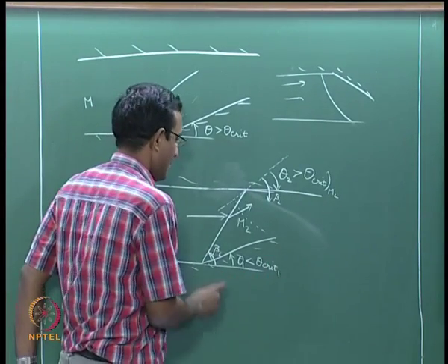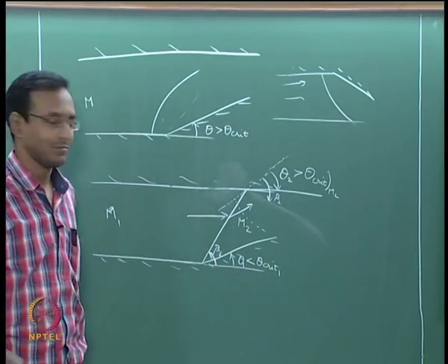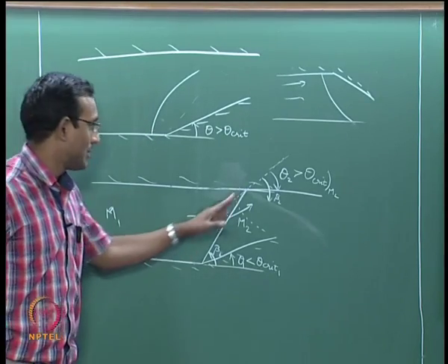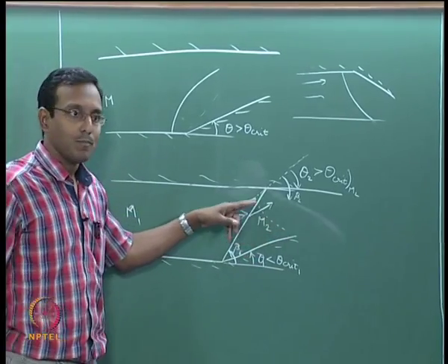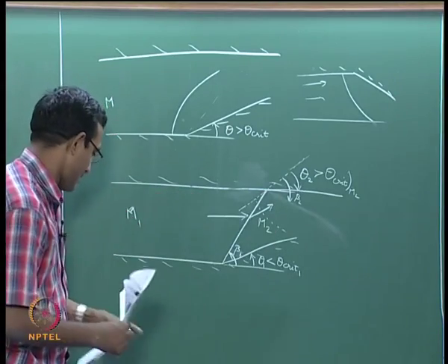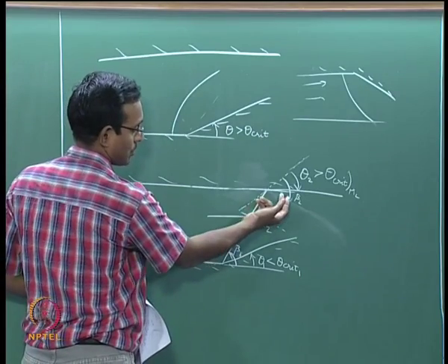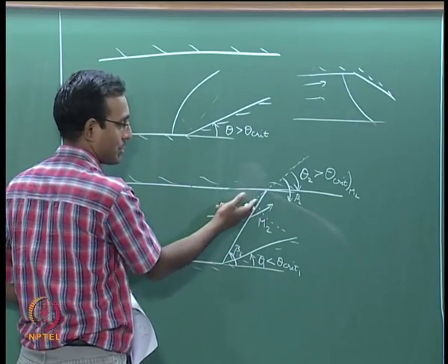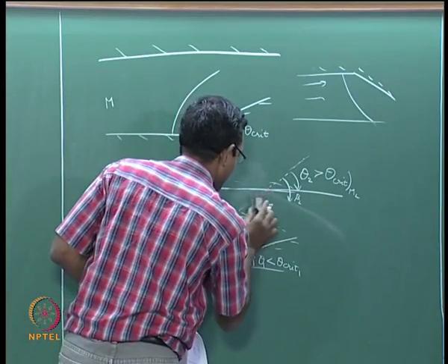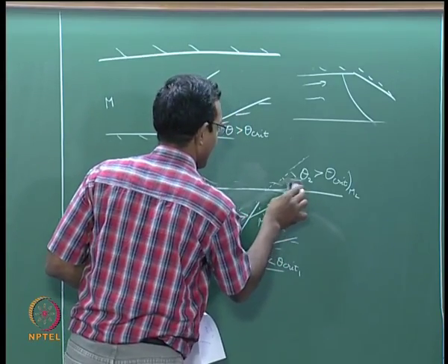If that is the case, what happens to this shock? That should merge with this one and form something new. Okay. So I have come to a case where when this oblique shock goes and hits and it has to reflect, but the reflected solution should be above shock. If I think that, then my solution changes. I will just erase some parts of it because the post shock solution should come ahead of the previous shock, which means I have to erase this shock up to some region and I will redraw it. No more beta 2, so I will erase that beta 2 arc. Everything else stays.